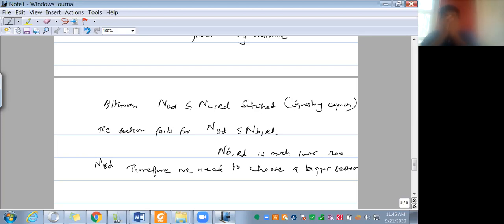So this is how you approach a beam problem, a column problem. When you have a column, you have a design action load from the support reactions. The support reactions of the analysis will provide you the required capacity.